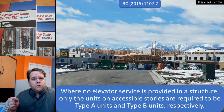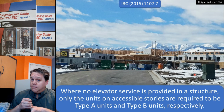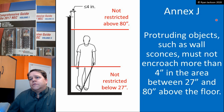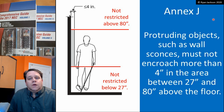Now, once we've established that we're in an area that needs to be accessible, commercial buildings, apartments on the main floor, Type A or Type B units, what are the requirements? This is where you can go to Annex J in the back of the code book and you can see the rules. The first one is for protruding objects such as wall sconces. They must not encroach more than 4 inches in the area between 27 and 80 inches above the floor.